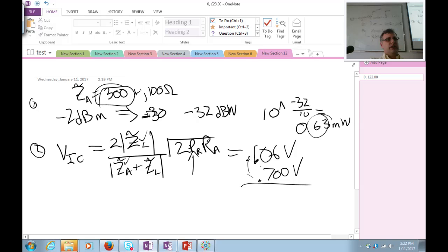Well, that's going to be 700 millivolts, 0.700 volts. Is there enough to actually meaningfully convert in this scenario? If I have negative 2 dBm and an antenna and an integrated circuit connected to each other, does that system pull enough power out of the air?